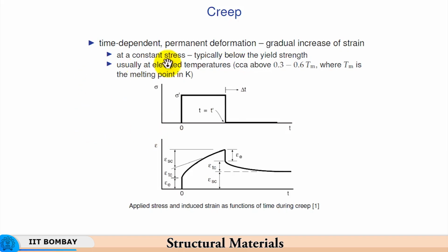Now, a key typical characteristic of creep is its viscous response, in the sense that it is a non-linear response to a linear stress variation. So, you see that instantaneously the stress rises to a specific value, it is held constant for a given period of time, then it is dropped very rapidly, and then maintained at 0 level for a relatively prolonged period of time. Now, if you look at the strain in the material, it does not respond like what we would expect at room temperature.